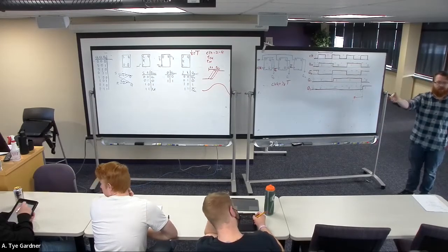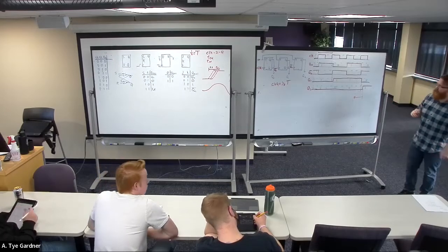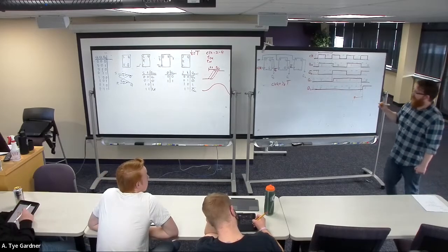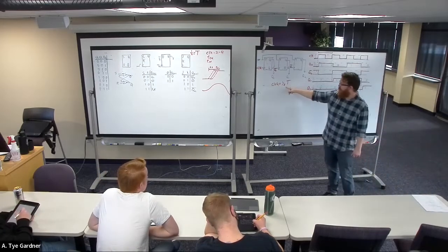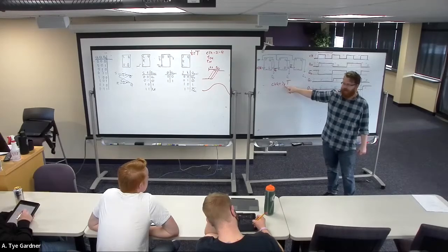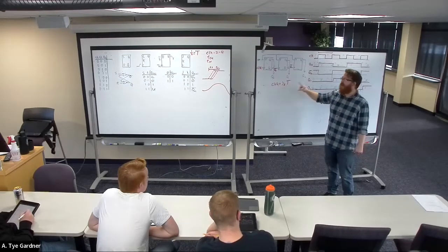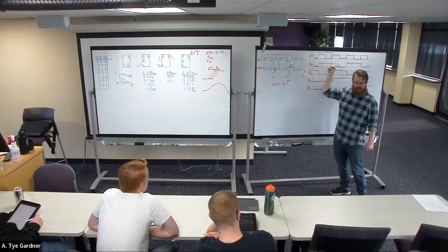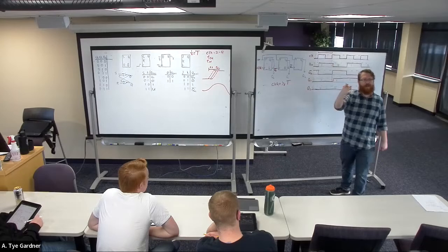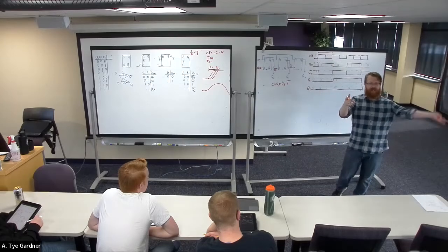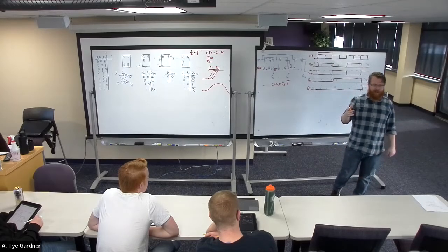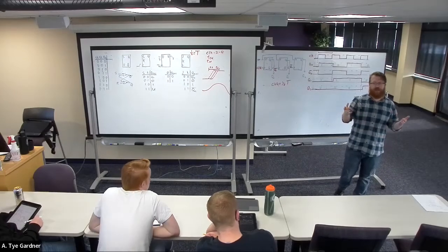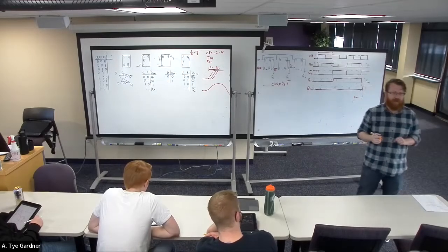It has an accumulative delay, which is to say at this point, if I ever get to the point where I've done 8 in a row, if I've stuck 8 in a row together, that means that my last one, my 8th toggle, won't update until the first toggle has started changing to the next number, and we will never see a correct number. So we've inflicted a speed limit on our 8-bit counter.